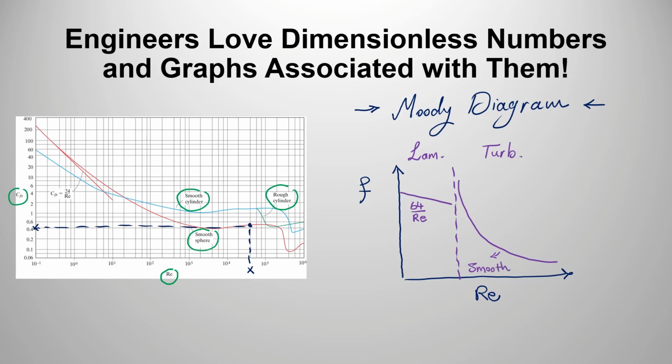Now, based on the theory of dimensional analysis, they came up with dimensionless numbers that represent the problem, namely Reynolds number and friction factor. And they sketched these lines for laminar and turbulent flow. But then they asked another question: what if the relative roughness of our pipe changes? And then they added another dimensionless number to this graph. And what was that dimensionless number?